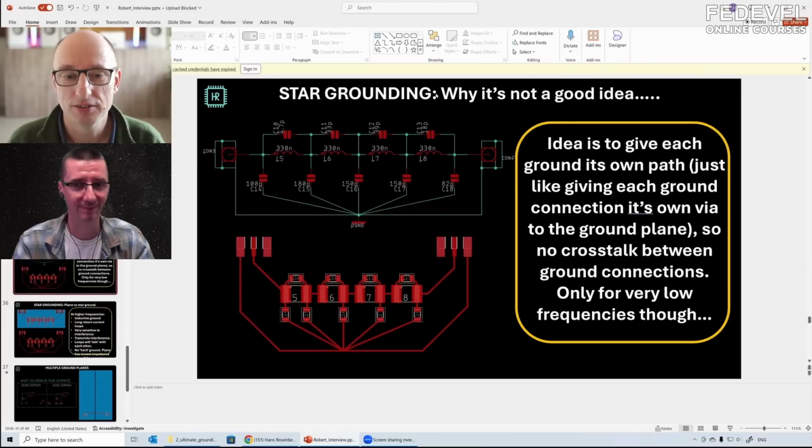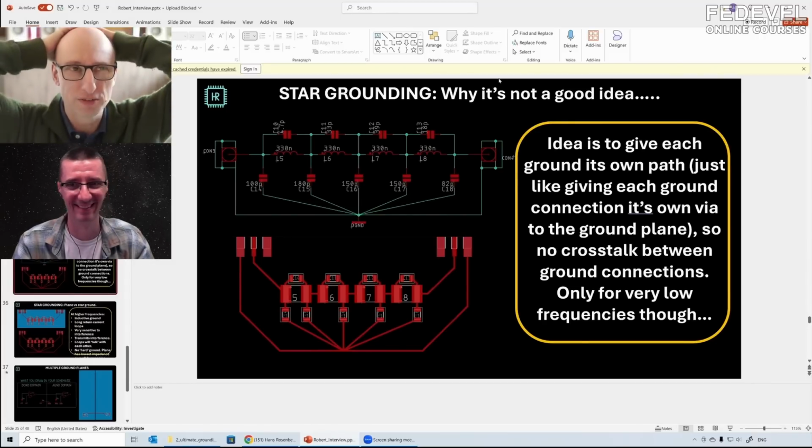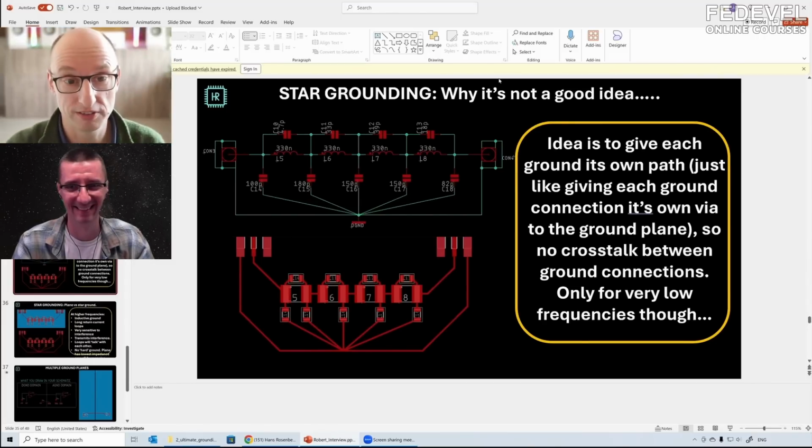Yeah. So I made one video about common bad advice. We already discussed the split ground planes, which I keep finding in data sheets. It's amazing. And the other one, which is very persistent, is star grounding. And I never understood where it came from until I made this video on YouTube, because someone in the comments said, yeah, well, this basically comes from the old days when they were making tube stuff and things like that. They didn't have boards usually. And then star grounding was a really good idea because you couldn't make planes. So the next best thing then is a star ground.